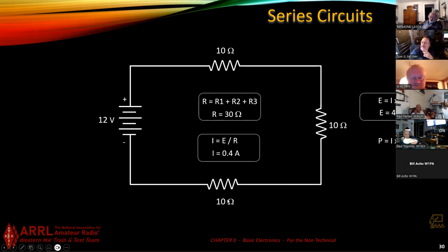But I can guarantee you with 10, 10, and 20, I don't even have to think about it. And as you grasp the concept, you'll understand this. I know 50% of my resistance is right there. So guess how much of my voltage drops right there? 50% of my voltage. 6 volts, 3 volts, 3 volts. If you do the math, you'll prove that out.